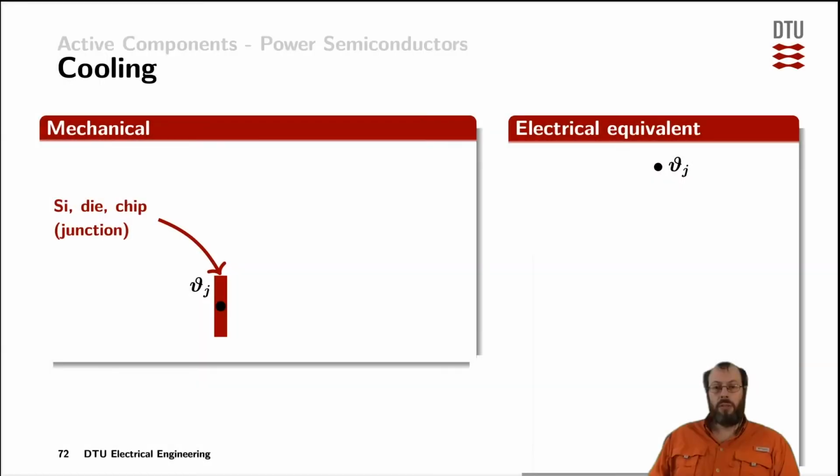Now we've experienced already various mechanisms to have power dissipation in power semiconductors. Power semiconductors are using silicon technology, most of them, also GaN technology or silicon carbide. Now, typically you start the thermal modeling with a die, with the chip, or also called the junction.